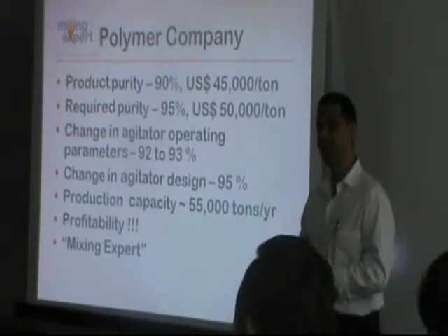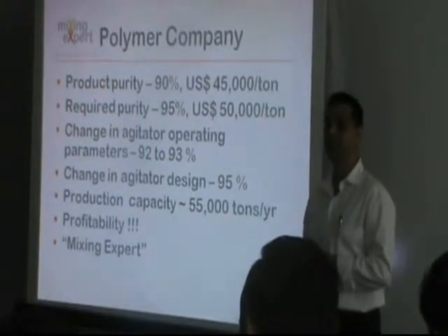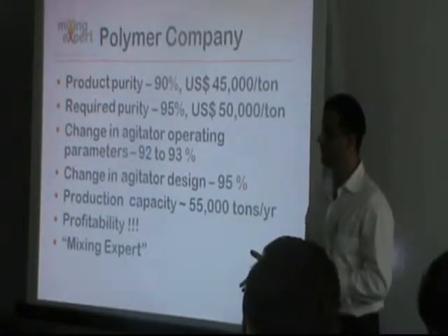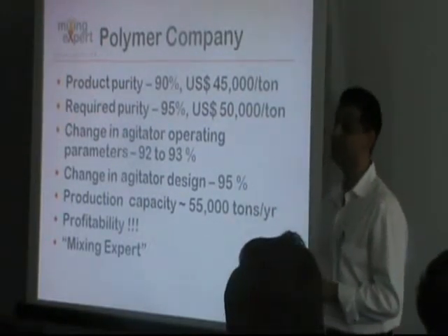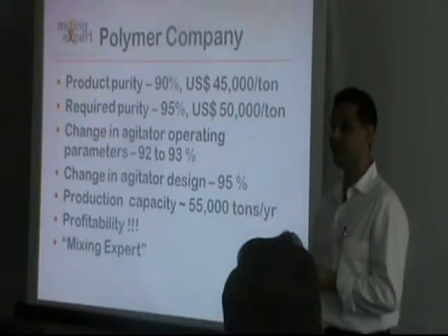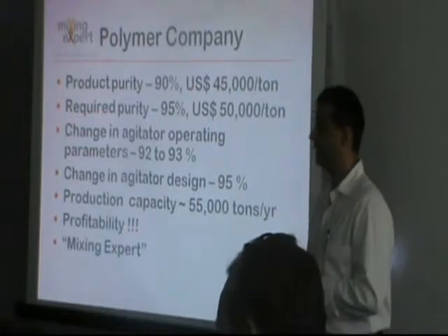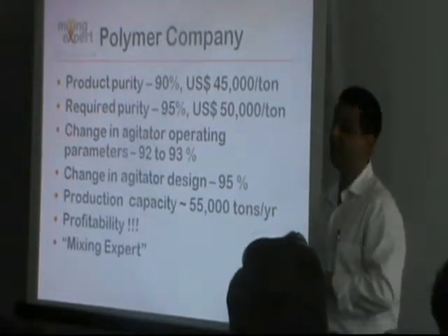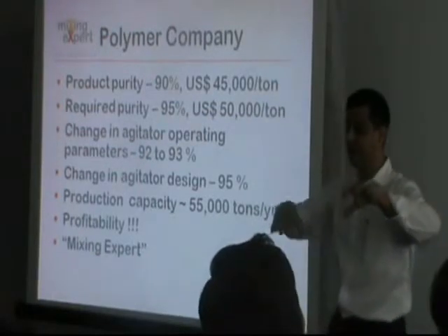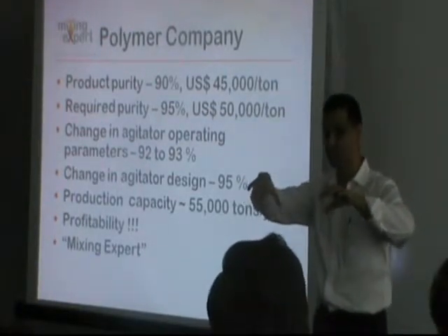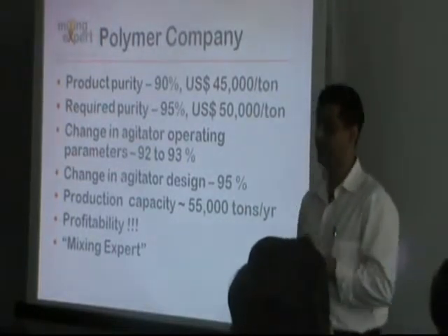As we moved forward, they had a requirement for fresh equipment, and that is where we could design the equipment from scratch. With these two aspects, we could increase the level of turbulence. But with increasing the diameter and increasing the speed, we increase the vortex formation, and that had to be controlled. Also, because the agitator was off center, there was still a portion where the degree of mixing was relatively lower. So we had to install some baffles there.